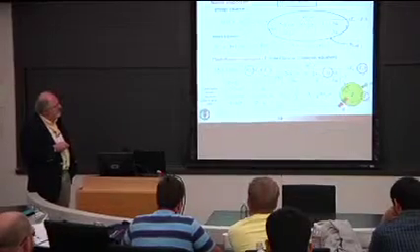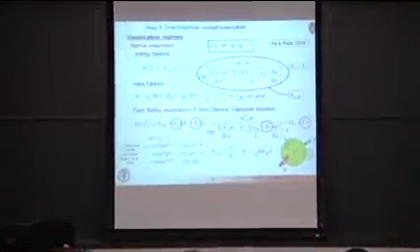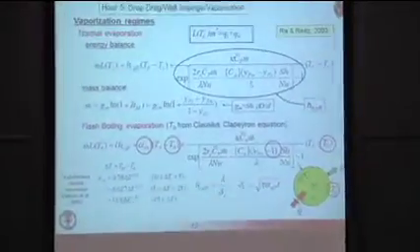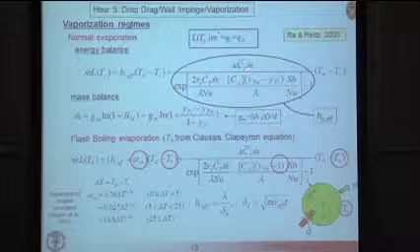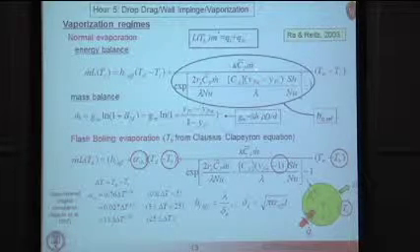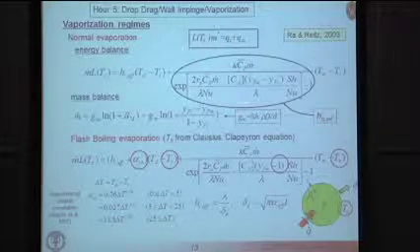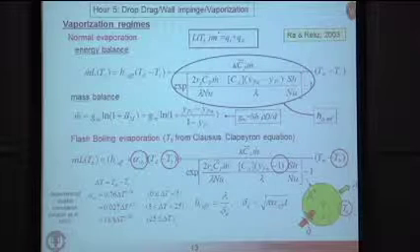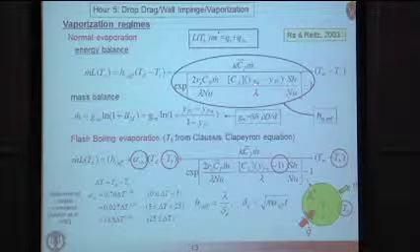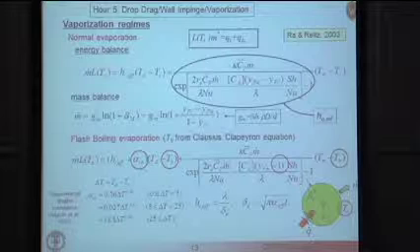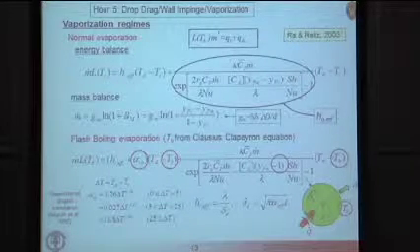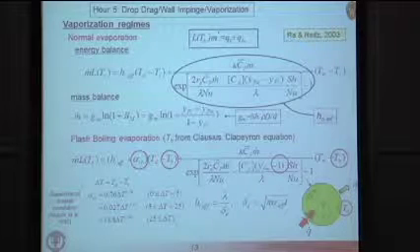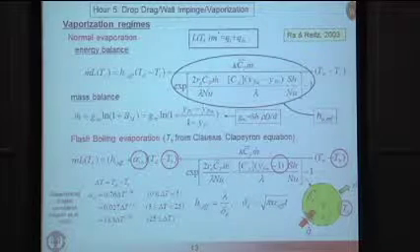This term in this ellipse here is the effective heat transfer coefficient, which is derived in this paper here. It depends basically on the mass transfer rate, Nusselt number, thermal conductivity, Sherwood number, and the difference between the fuel concentration far away from the drop and the fuel concentration at the drop surface. And other things, drop size and specific heat and so on.